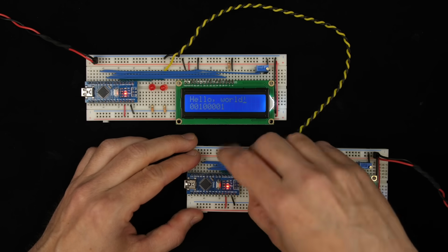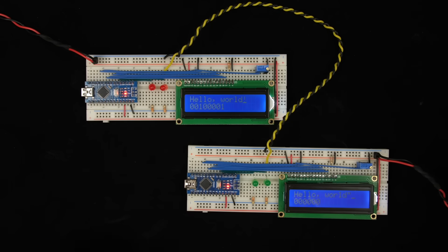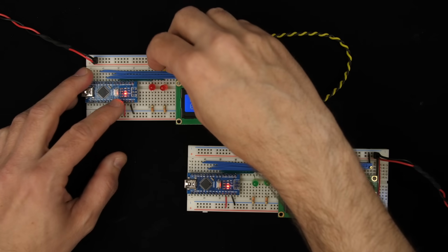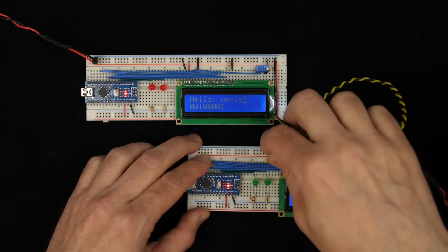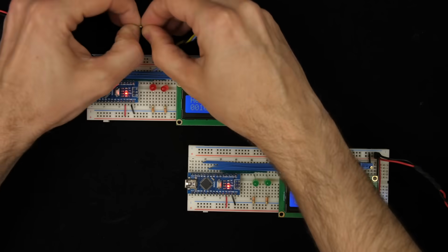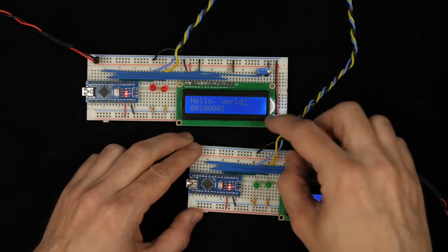And same thing here on the receiver. I'll connect pin 2 in the same way to an LED down here. And finally, instead of just these two wires connecting data and ground, we're going to need 3 wires connecting clock, data, and ground. So I'll hook up clock, data, and ground on our transmitter. And then the other end here, I'll connect clock, data, and ground on our receiver. And so there we go.